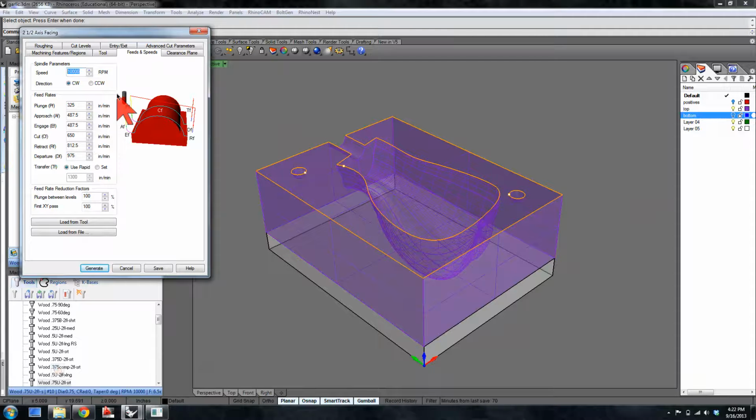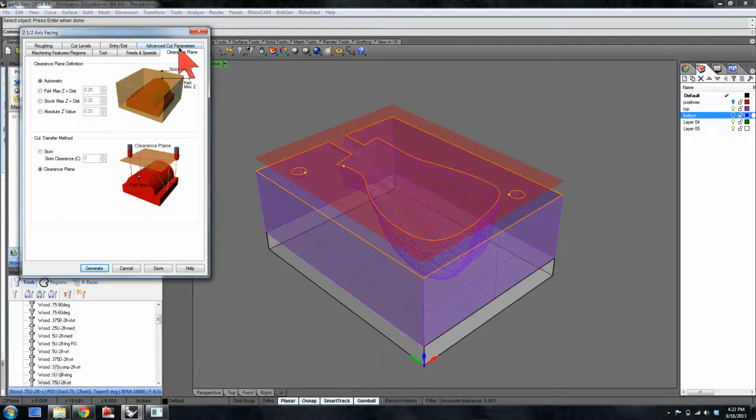Spindle speed is something that we tweak to try to get the best possible cut and chip combination. As you come into the shop, that's probably something that will help you adjust. The feed rates also are generally recommended, but not in any way absolute, and these are numbers that we tweak quite frequently, both in the tool library and in the shop when you come to cut your parts.